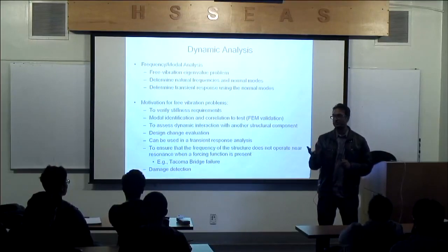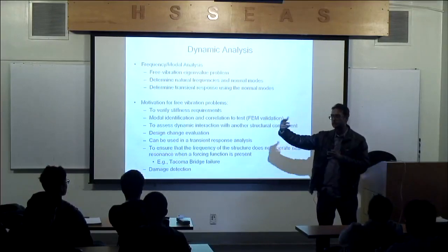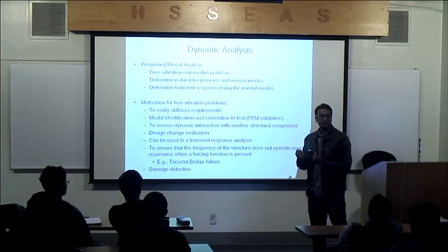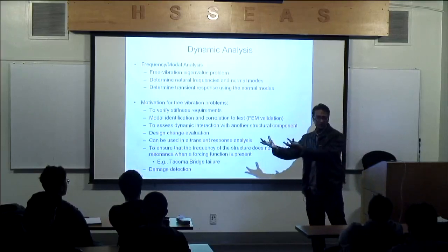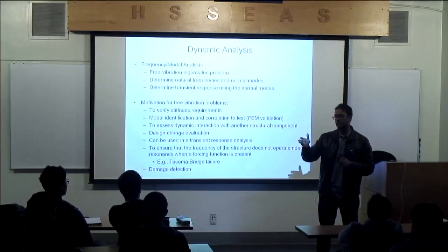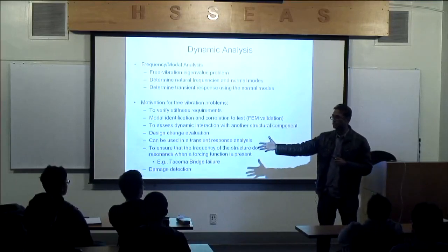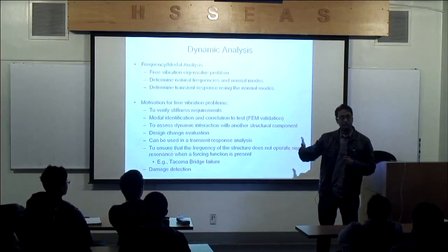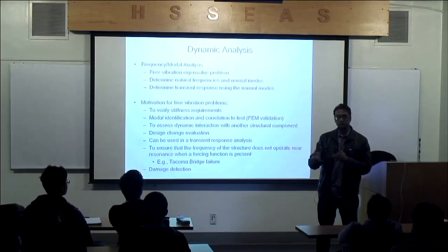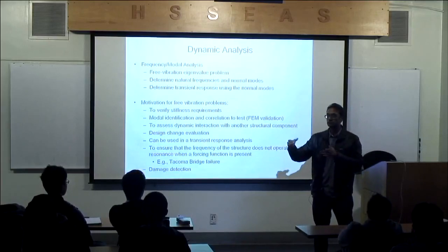By gathering accelerometer data from real structures. When the structures are in service, if there is damage occurring, I can take that signature and process it to study its dynamic characteristics. And if the dynamic characteristics show that they have changed over time, maybe it's because the stiffness is decreasing. Don't you agree that if there's damage, stiffness most likely will soften, will change?